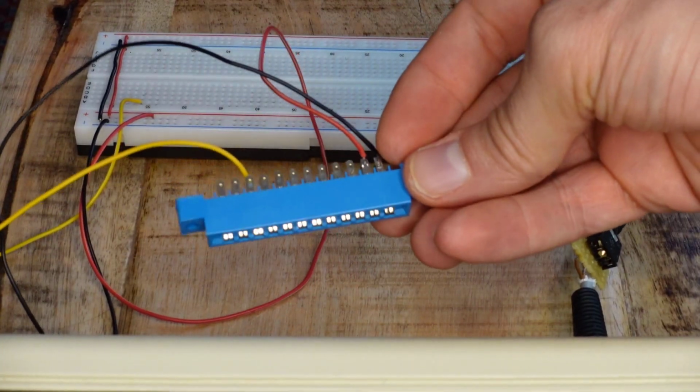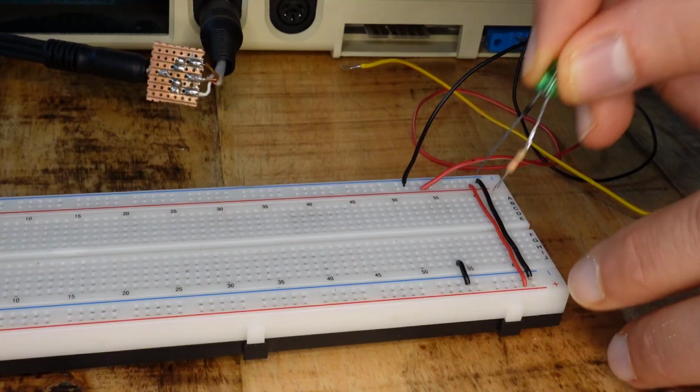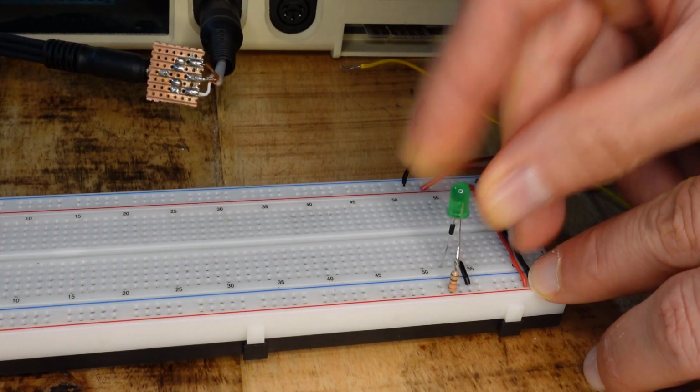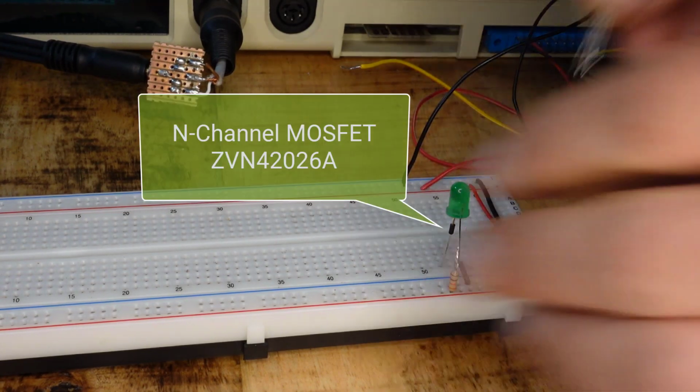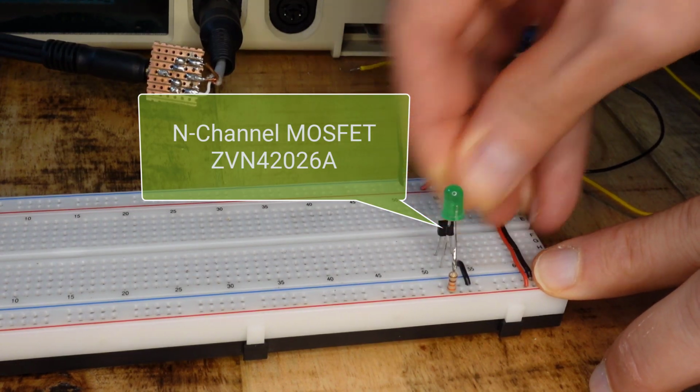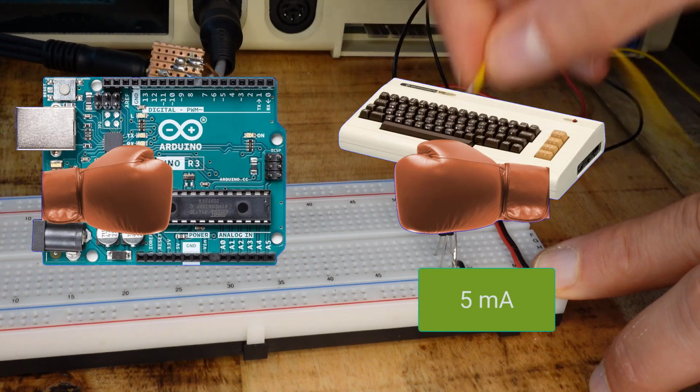These can easily be accessed by an edge connector. I want to let an LED blink now, but because the wire can only deliver a few milliamps, we need a transistor to even drive a small LED. An Arduino pin on the other hand can provide up to 40 milliamps.